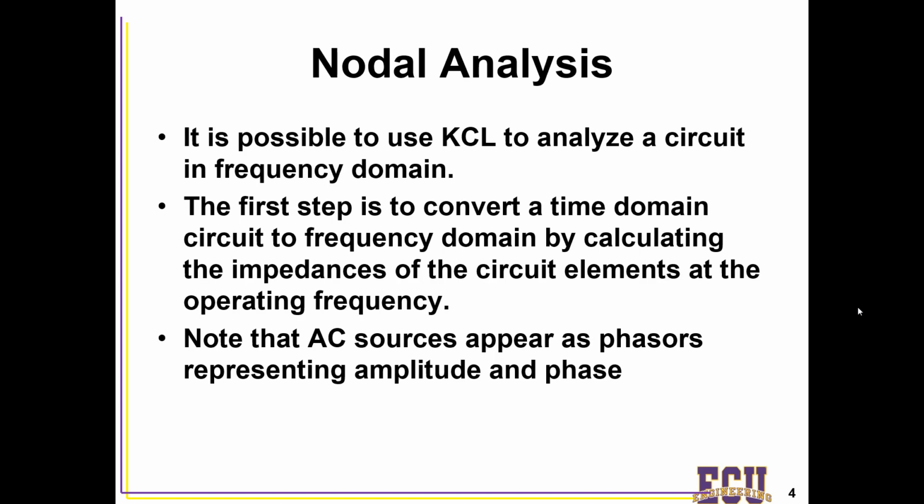So, nodal analysis. Here, we're just applying Kirchhoff's current law, and that certainly works for any circuit in the frequency domain and the time domain. Again, the first step is to convert that into the frequency domain by calculating the impedances of the circuit elements. So now, we're not going to be worrying about those first-order differential equations, second-order differential equations that we did previously when we were talking about RLC circuits and RL circuits. Now we're going to be thinking about them like resistors that have a complex impedance that is frequency dependent.